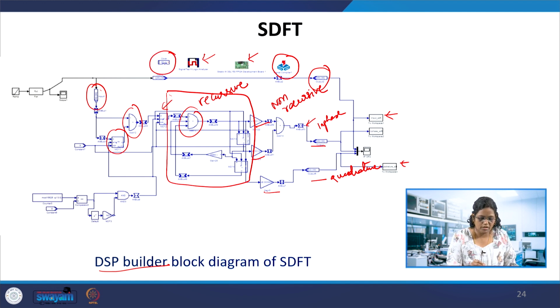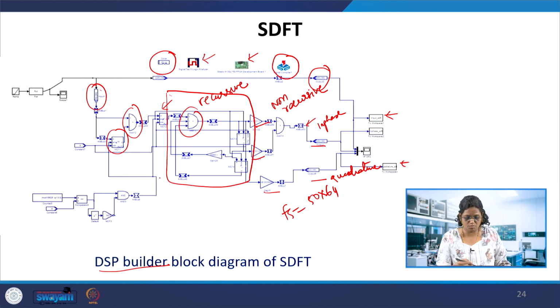So there is a clock over here. It's a global clock which depends on the board which you are using. Every FPGA board will have a clock, which here is 20 nanoseconds, actually a 50 megahertz clock. So you represent this as the clock, and these decisions are based on this clock frequency, 20 nanoseconds. And 20 nanoseconds is very high for this. To match the outputs we got in Simulink, just a 50 hertz signal is used. So 50 into 64 is the FS we are using: 50 hertz and 64 samples per cycle. That's too much, but we want to show the smoothness of the waveform.